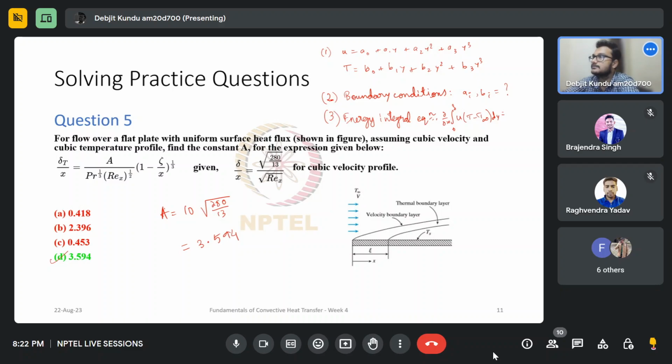Yeah, equal to this constant heat flux over rho Cp, which is the heat capacity of the fluid. So once we know u and T, using all this, we can find out what delta T would be in terms of delta T by x, and many other terms will be there. Prandtl number to the power 1/3, Reynolds number to the power half, and so on.